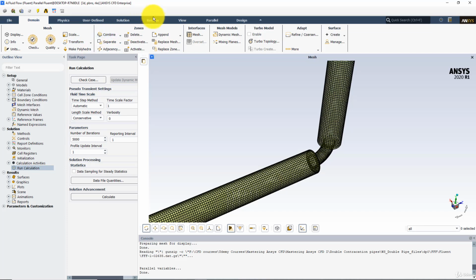And if I display especially the y plus value, the y plus value is a measure of how close our first cell is to the wall. And as you know, there are three layers of the boundary layer. One is the viscous sublayer, second is the buffer layer, and third the log layer. And when there's a separation zone, we must be resolving the viscous sublayer as well, because separation cannot be predicted very well without resolving the viscous sublayer and buffer layer. And for that case, we need the y plus value around 1 or 2, not more than 5. And now I'm going to check this.